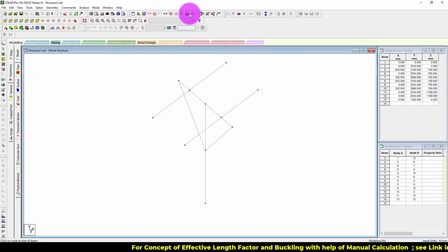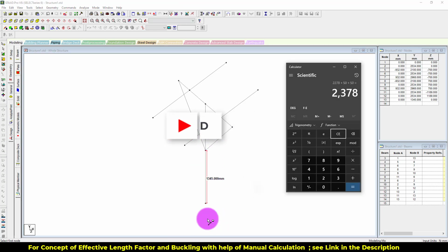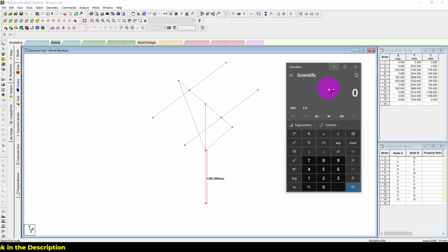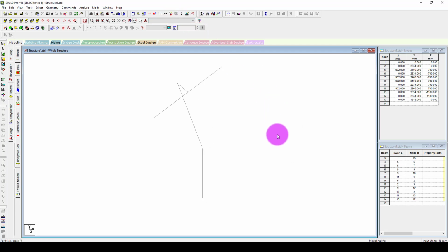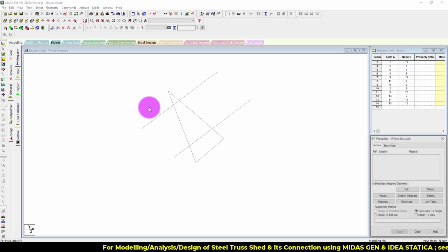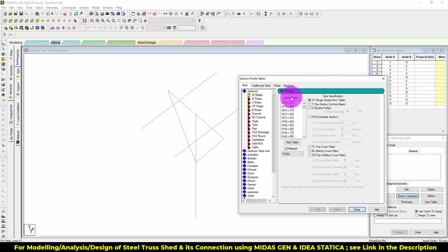Alright. Now the clear height under the structure up to the brace is actually 1345 millimeters, which is actually 4.5 foot. Alright. Now this is the structure, and now we will be going towards the section definition. Go to the general tab, go towards the section database. We will be using W section for the beams initially.